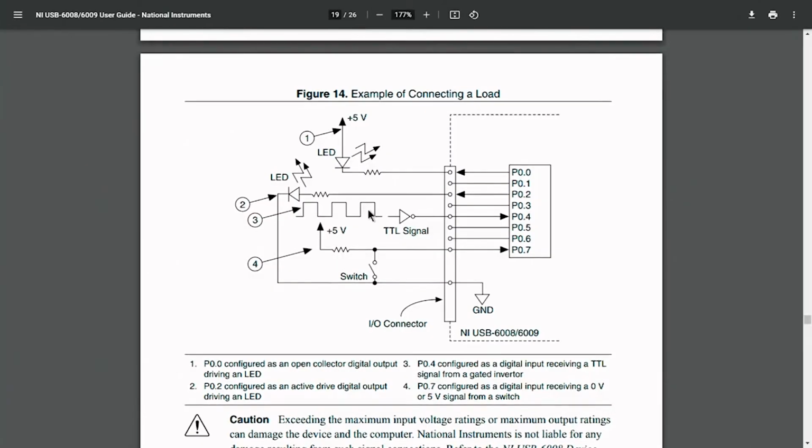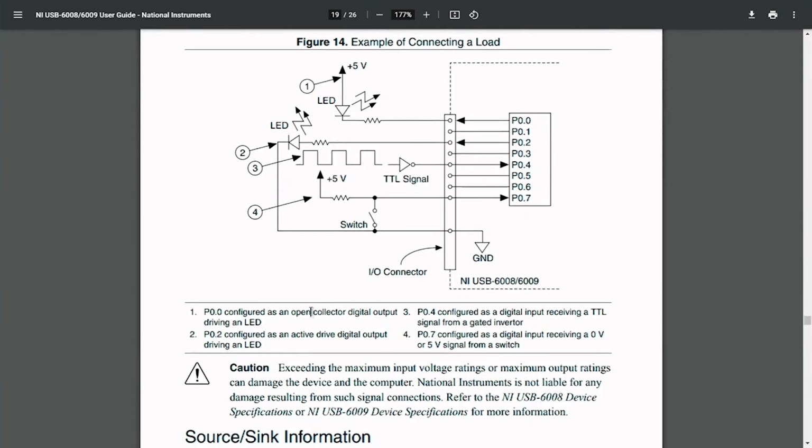We may have to design a driver circuit using a triggering circuit, so that for the triggering we can utilize the digital outputs of the microcontroller to trigger on and off, whereas the power required for the load can be taken from the main source, right. The digital configurations, where a line can be used as both input and output, can be used here. So complete information about how to interface can be seen.